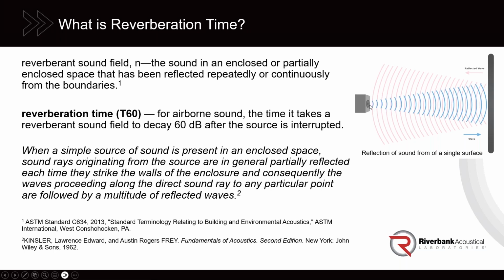So what you have with reverberation is not just a single reflection, but a compounding of countless reflections off of every surface within the room, which are arriving back at the listener at different periods over time. So this reverberation, in most cases, is detrimental to the function of a space.